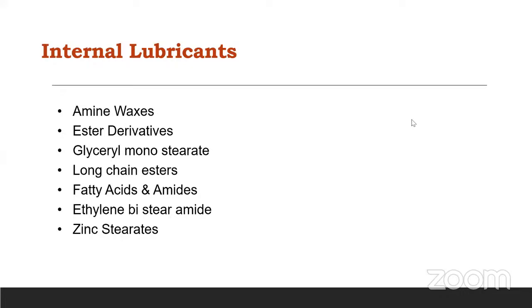So for a polypropylene system, if PP is being processed, film formation needs to take place. Generally, we need to see what kind of stabilizers or structures have been used till now for PP, and then zero in on which external lubricants are being used. We can narrow down which can be suitable for which.